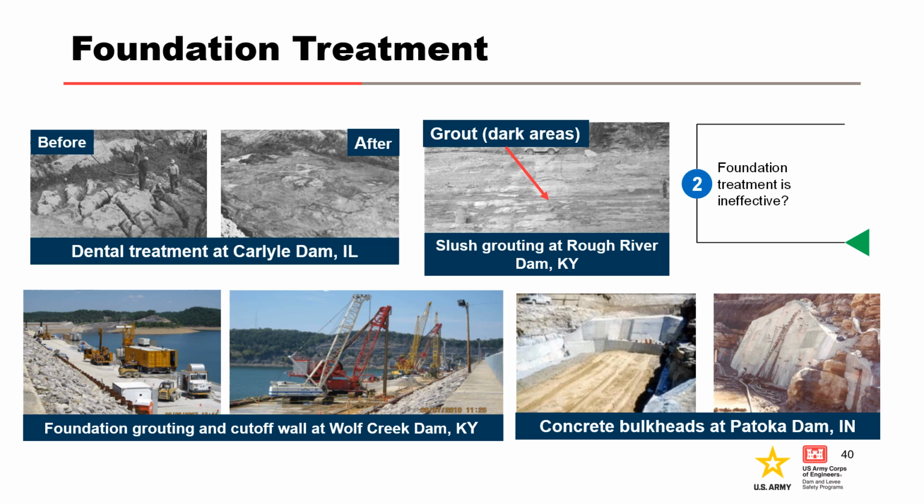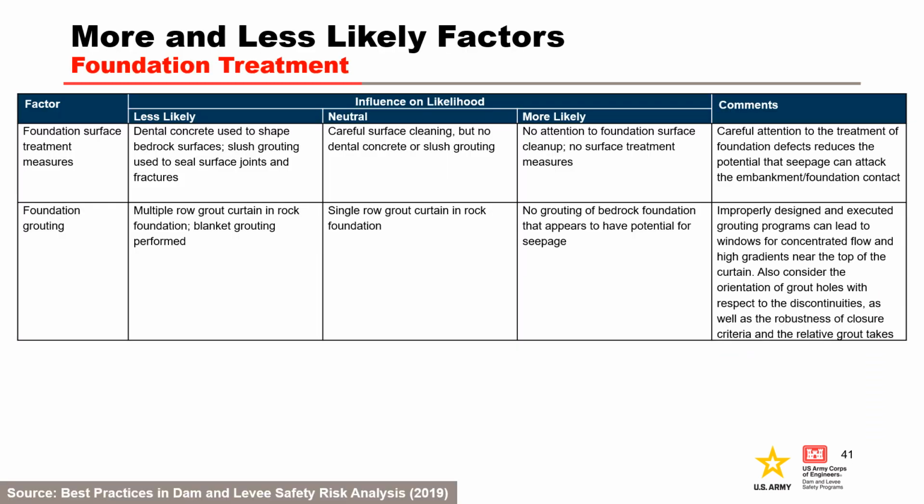Be wary of a reliance on grouting to serve as the sole design feature to control seepage. And consider information in the foundation report, construction photos, geologic mapping, as-built drawings, performance, and instrumentation. This portion of the table from best practices can be used to help assess the likelihood of foundation surface treatment and foundation grouting not being effective.